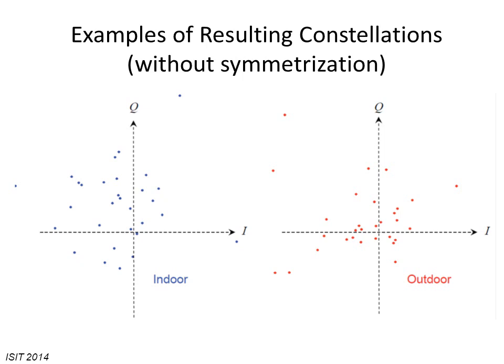As you see, the points are randomly distributed in the I and Q coordinate system. These points have an IID Gaussian distribution for their components, and the mean of that Gaussian is 0 and the variance is 1. As I mentioned before, and I will later show an example, these constellations can be symmetrized. We can introduce symmetry in them by modulating another bit into the sign of I and one other bit to change the sign of Q. Consequently, we get four-way symmetry in the 4 quadrants.